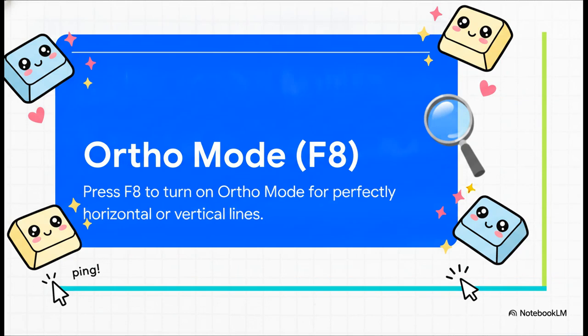And this brilliantly illustrates the solution we all know, Ortho mode. But again, it all comes down to how you activate it. If you're moving your mouse all the way down to the status bar at the bottom of the screen to click the Ortho toggle mid-command, well, you're reintroducing that exact same workflow friction we literally just eliminated. You're pulling your cursor away from the active drawing area.